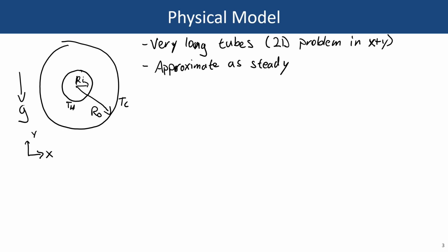Okay, next, if we look at this domain, it's actually symmetric around the midplane. So we could say that this is going to be symmetric around that center line drawn here. That gives us another way to simplify our problem. So this is going to be a symmetric problem around that center line.